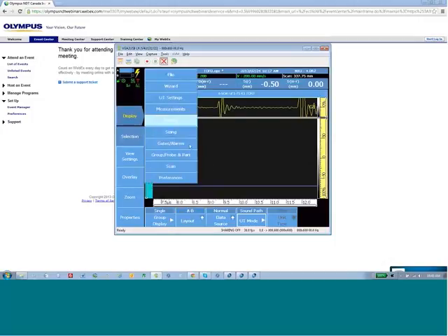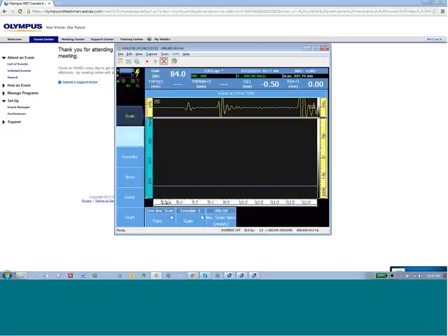Going to the scan menu, we're going to change the default from time to encoder 1. This is telling the software that we are now going to fix the pulsar at the speed of the encoder. When I move the scanner, this B scan will start to build, and I must enter in the parameters of the encoder, which can either be entered if you know them or calibrated using the encoder calibration wizard. The area of the plate and the inspection resolution.